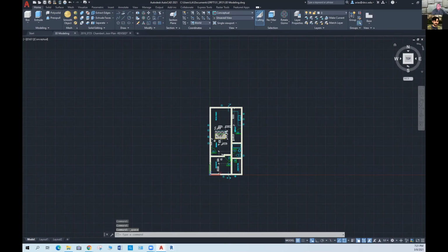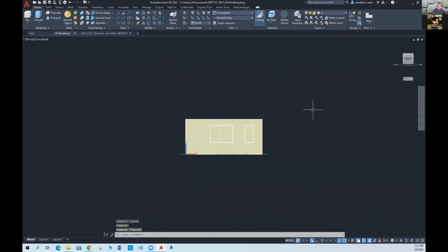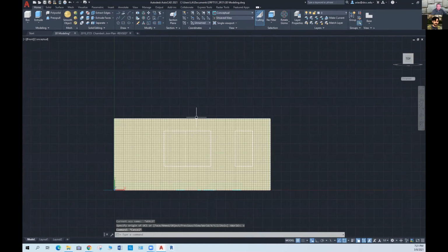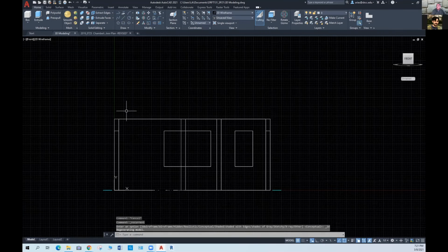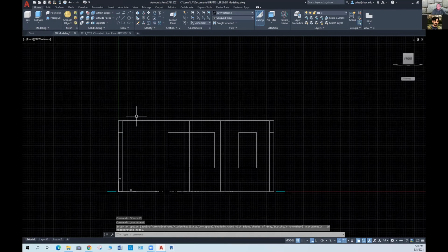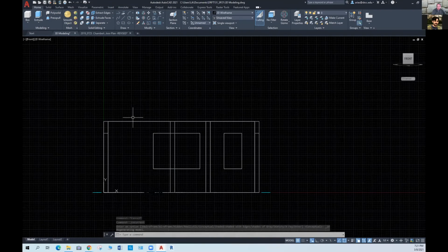And now I can go to this side here. Now I can do UCS by view. Now I can actually draw here and I'll be fine. And so do a wireframe view. If you have the section, the easiest way to do this is to just place the section here. Otherwise, I'm going to do this.